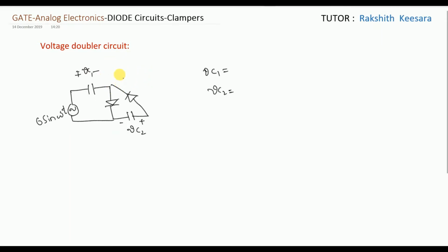So this is also a previous year question, guys. See, if you observe here, this is the direction of current. So this is also a voltage doubler circuit. Next, what is the next step? Draw the polarities of the voltage. Since it is 6, it will charge to 6 in this direction, and the direction is like this. So it will charge to 12 in this direction.